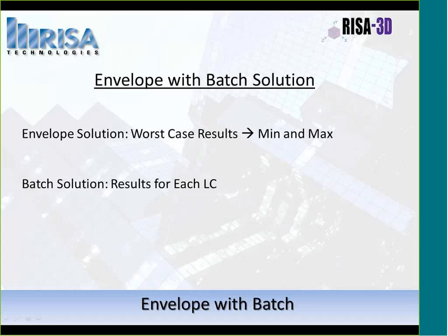Everything you're seeing is based on the minimums and maximums of what got run in that entire load combination selection group. So it's often a smaller solution file because you're just looking at those two values for each member or each joint, minimum and maximum.